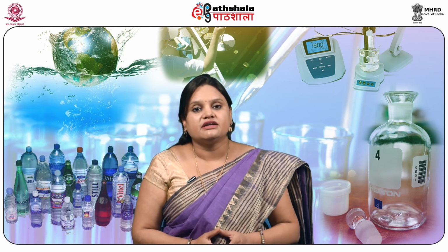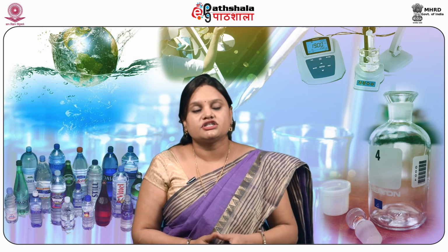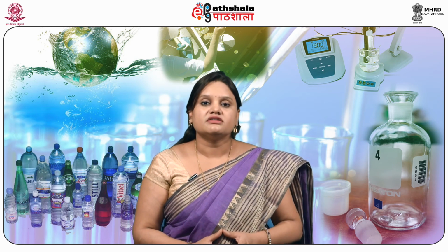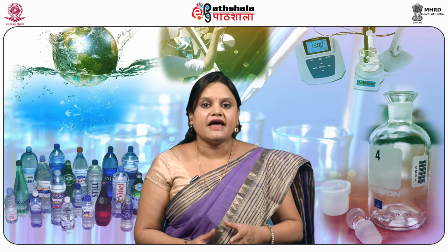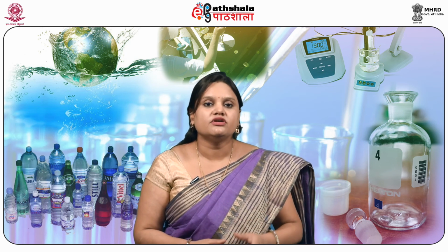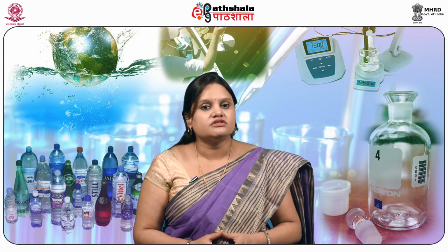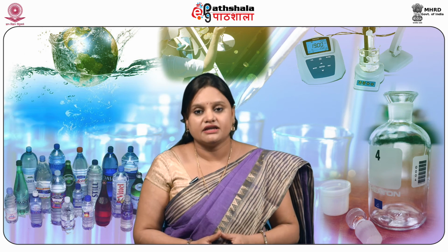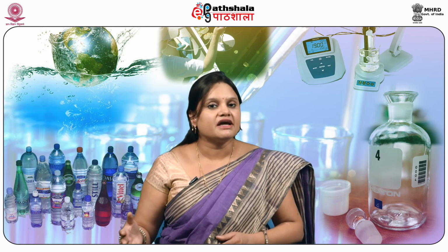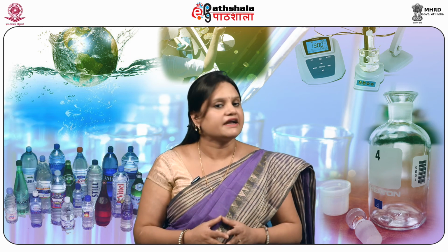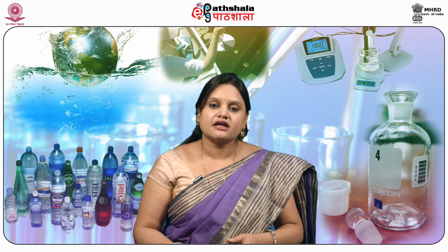The next method is known as water or steam injection. In this method, the injection of water or steam causes the stoichiometry of the mixture to be changed and adds steam to dilute calories generated by the combustion. The next method is reduced air preheat. In this method, air is usually preheated to cool the flue gases and reduce the heat loss and gain efficiency. Then the last method is known as catalytic combustion.